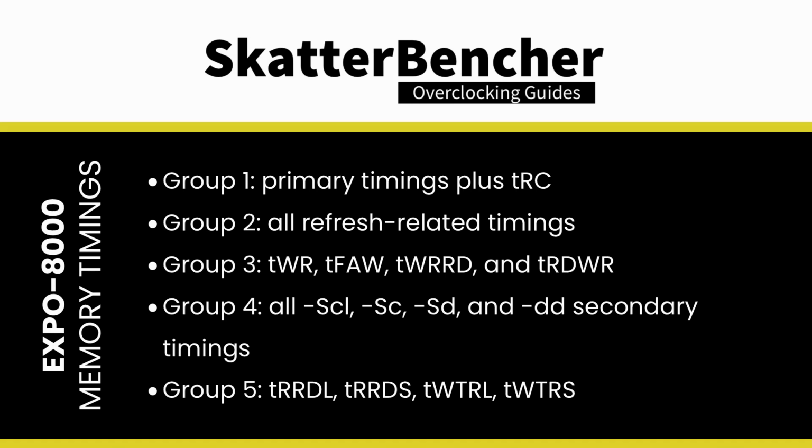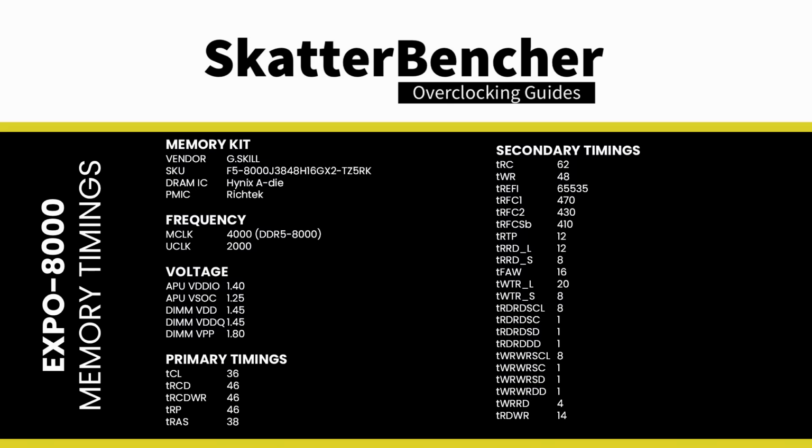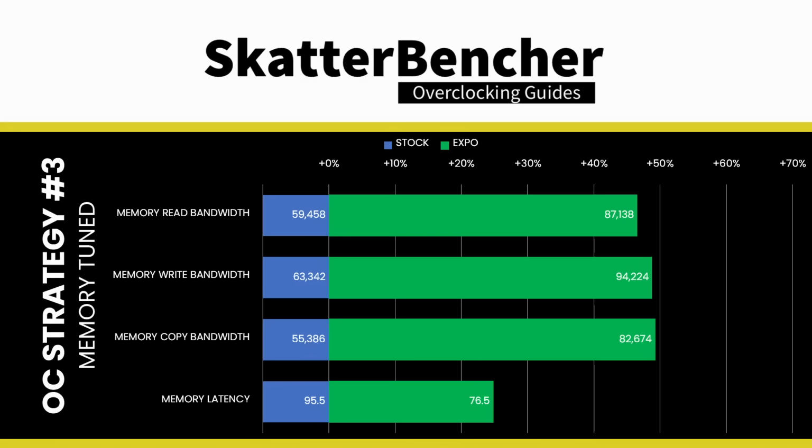By checking the impact of adjusting each group's memory timings, I found that it was the L and S suffix subtimings causing the memory instability. By relaxing those just a bit, the memory was stable. Here are the final optimized memory timings for this memory kit. After the tuning, our ADA64 performance improved quite significantly. We got about plus 50% extra bandwidth and plus 25% better latency by enabling EXPO.